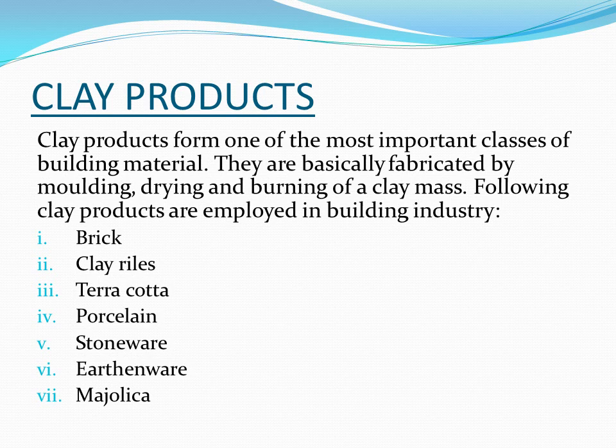You must remember that the higher the bulk specific gravity, the stronger will be the clay products. However, this rule does not hold good for vitrified products since the specific gravity of clay decreases as vitrification advances. The bulk specific gravity of clay brick ranges from 1.6 to 2.4.